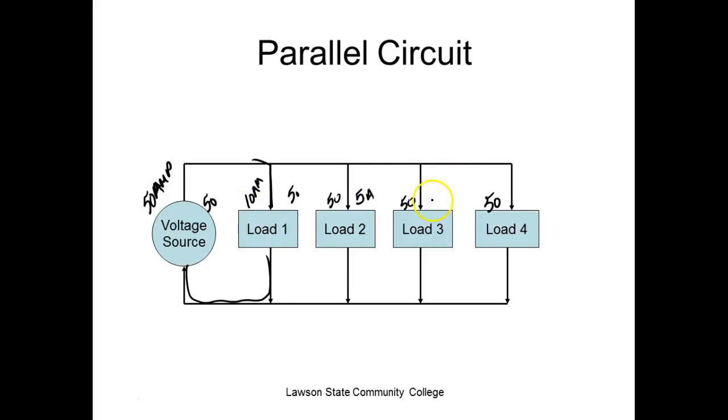Okay, let's say this guy right here is conducting 20 amps. Which one's conducting this one? Okay, so this guy would be 15 amps. So notice what's the same across all the circuits. Voltage. What's varied? Which one has the greatest opposition? Yeah, this guy right here. And this right here would have the lowest opposition. So in a series circuit, the biggest resistor does the most work. In a parallel circuit, the smallest resistor does the most work. These suckers are just opposite.